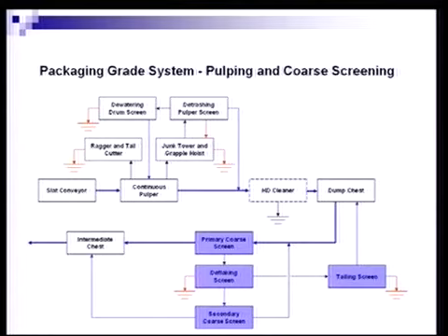flakes in particular. Those accepts from the deflaking screen will then go to a secondary coarse screen, which is much like the configuration of the primary coarse screen, and its efficiency is going to be approximately equal so that the pulp produced in the accept stream can be fed forward. Doing so makes the entire system smaller, much more capital competitive and floor space competitive.